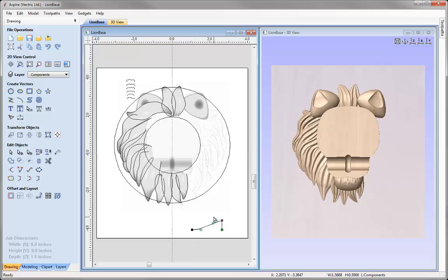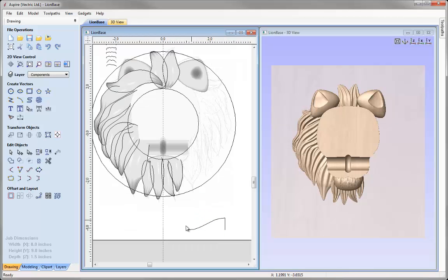I'm going to select this node first, shift and select the handle and press Y, and then I could just tweak the shape of this cross section. The idea here is we're going to come in at a flat shape at the bottom, and then it's going to rise up into this curvature and come in at 1/2 inch high. So we're going to come in flat, and it's going to raise up to 1/2 inch. Let's see how that works.